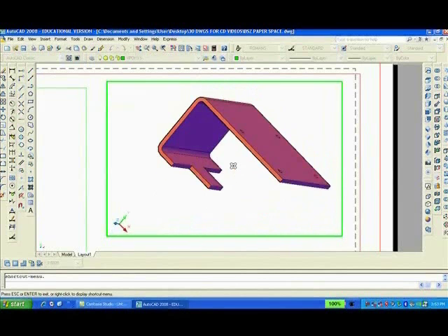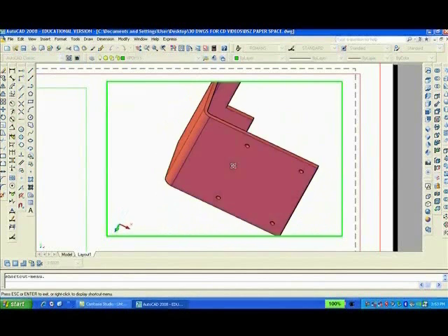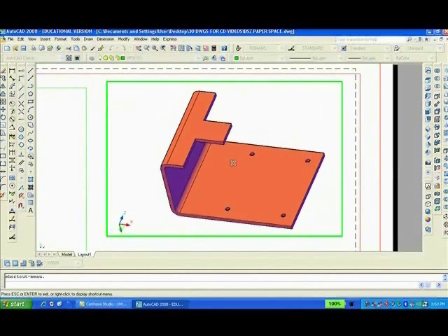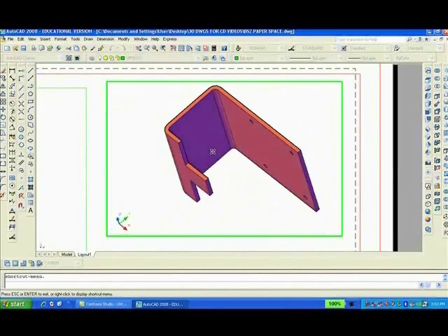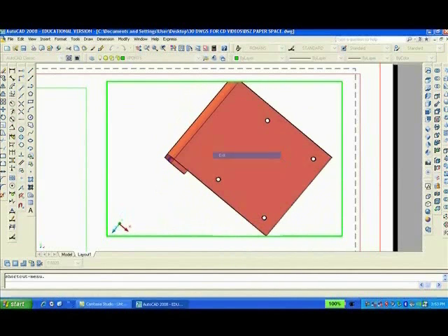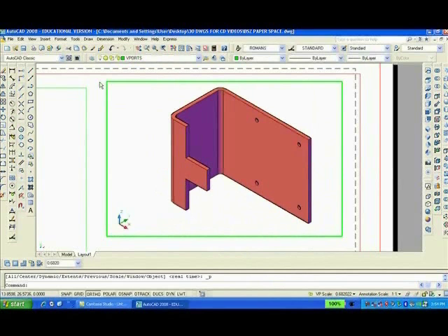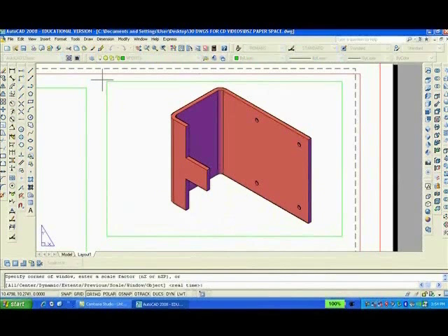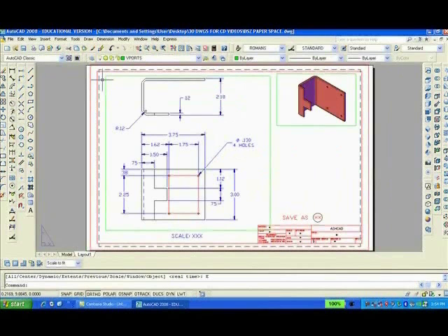The part looks okay, and so I guess we can put an end to this drawing. So I'll right click and I'll exit, and I'll zoom previous, double click outside, Z, enter, E, enter. Then you can edit whatever you want. You can put the scale, it's 1:1. You can put the drawing number, it's 24. You can edit these little asterisks, and you can put your name in there and the scale of the drawing, whatever. So that's about it.